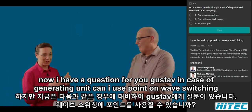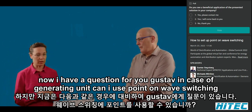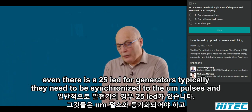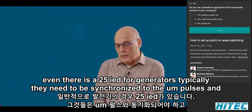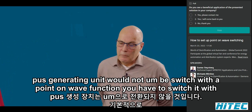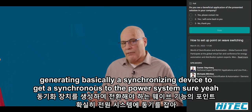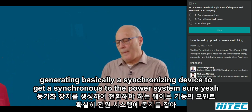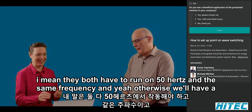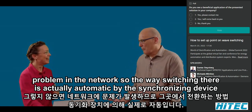But now I have a question for you, Gustav. In case of generating unit, can I use point-on-wave switching even there is a 25 IED? For generators, typically they need to be synchronized to the power system, because a generating unit would not be switched with a point-on-wave function. You have to switch it with a synchronizing device to get it synchronous to the power system. Sure. I mean, they both have to run on 50 hertz and the same frequency, and otherwise we'll have a problem in the network. So the point-on-wave switching there is actually automatic by the synchronizing device.